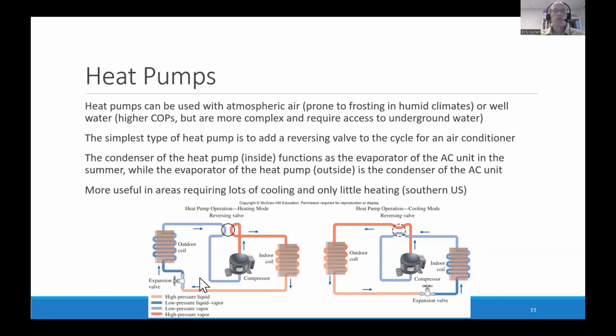Here are diagrams of heat pumps on the left and AC units on the right. They are exactly the same, other than what is deemed the hot fluid and the cold fluid. The definition of each is compared to the outside temperature, and the direction of travel of these fluids. Notice the change in direction from the reversing valve.